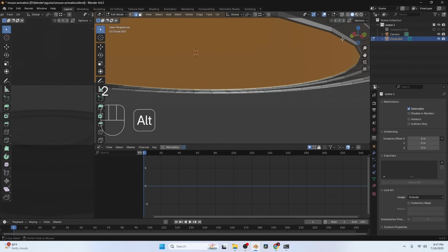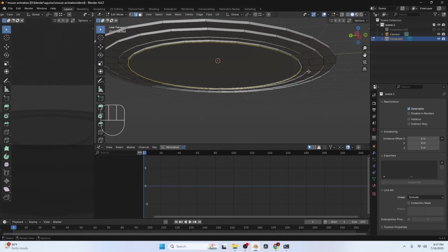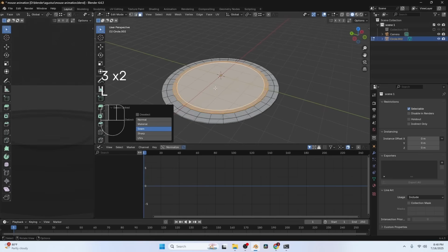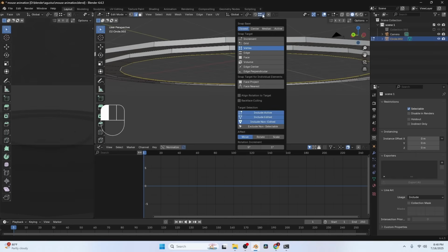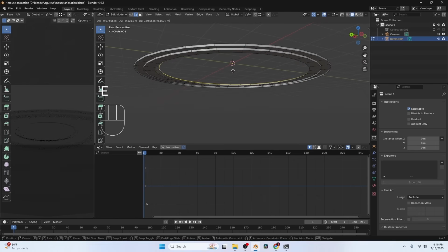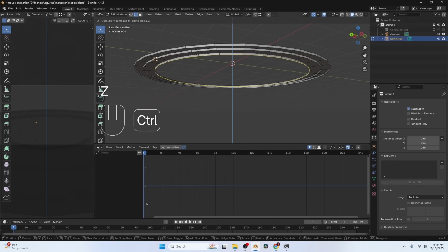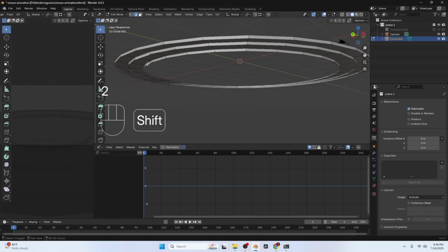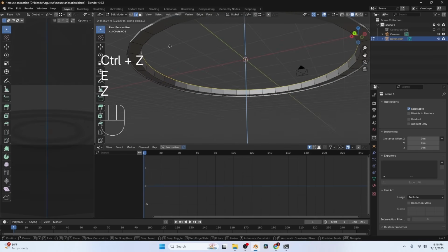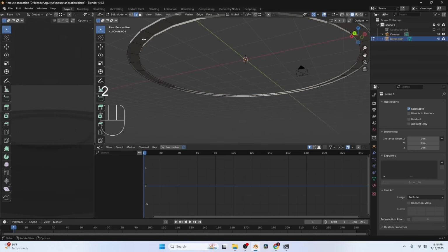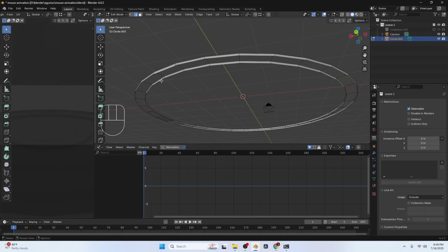Down here, click like this, then press F to fill. Then we can click like this, then H to hide. This one, change your snapping to vertices, press E, extrude it, Z axis, hold Ctrl, snap to this edge. Then select this edge and this one, press F to fill, just fill everything down here. Then we can L and hide this one, E, extrude, Z axis, just to fill everything here. Okay. Press Alt H.